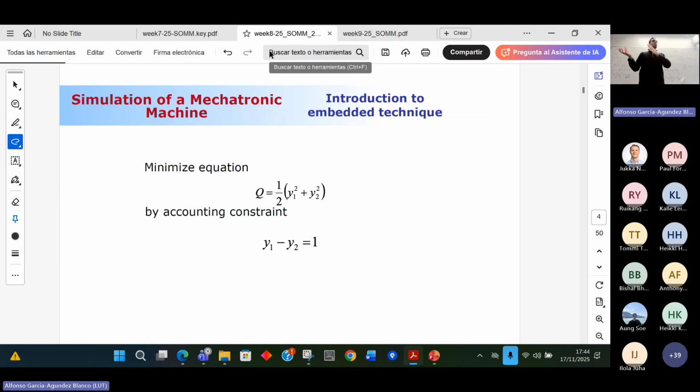You have a multi-body system with a lot of coordinates because you have modeled it in a systematic way, and you have said, okay, for each of the bodies, imagine that I have an arm, the body, the leg, for each of my bodies, you are going to consider the Cartesian coordinates and the orientation angle, no? What happens? The actual number of degrees of freedom is usually lower than the number of coordinates that you are modeling the system with, no? And you have a lot of constraints, given by the revolute joints, prismatic joints, relating these coordinates.